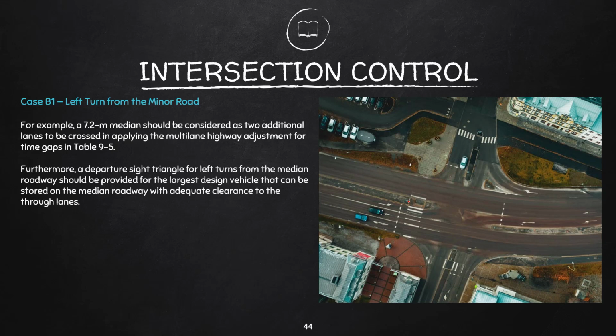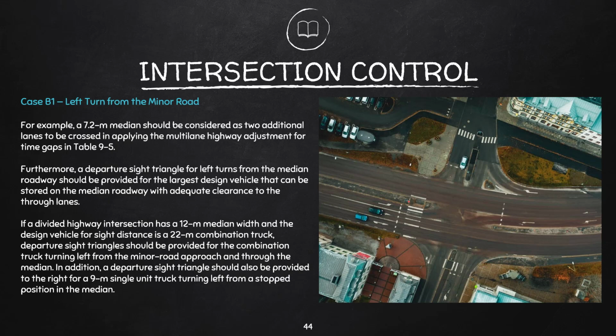Furthermore, a departure site triangle for left turns from the median roadway should be provided for the largest design vehicle that can be stored on the median roadway with adequate clearance to the through lanes. These are some additional considerations. You may just read on it.